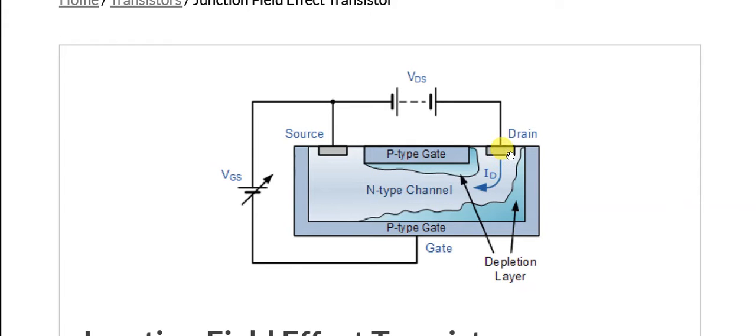From positive to negative, you see the drain current flowing through, but if the gate is less negative, the depletion regions of the respective junctions will shrink back close to the junction, and we have more cross-sectional area of the N channel where electrons are available and a larger current will flow.